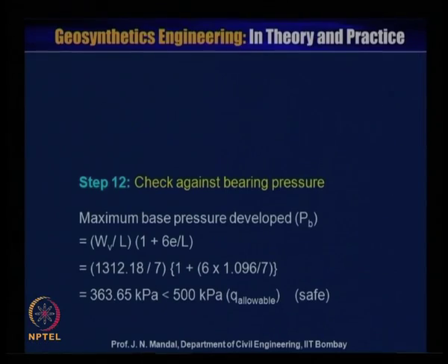So we check against the sliding, we check against the overturning, we check also the bearing pressure. So the wall is so far safe. So with this I finish my lecture today. Any question? Let me hear from you. Thanks for listening.